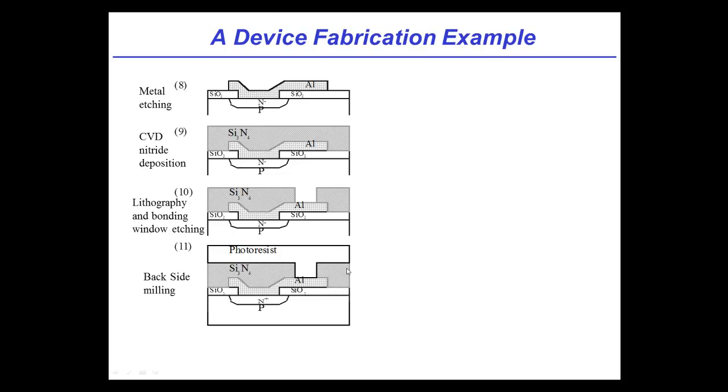But now there's an important step. You remember when we did the oxidation and there was a bunch of oxide on the backside? I need to clean that up. So you're gonna sand the bottom. Right. So what I do is I protect the front side, typically with photoresist, just so that it's saved while I'm flipping the wafer over to clean the backside. Right. So you don't scratch it or whatever. Exactly. And then I'll clean up the backside by, we call it backside milling. Typically that's actually mechanically done. You just polish it to clean it up.